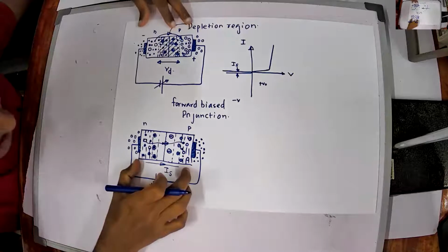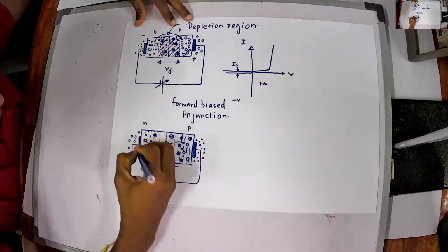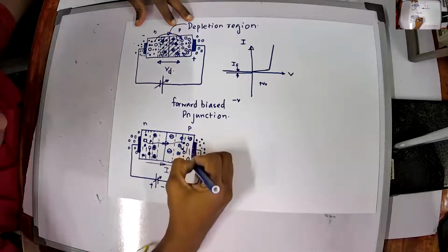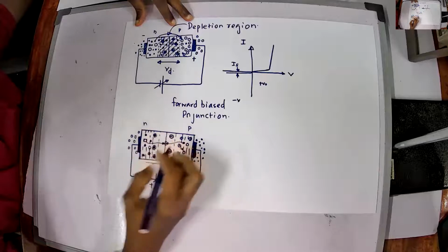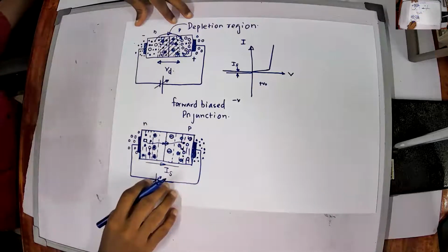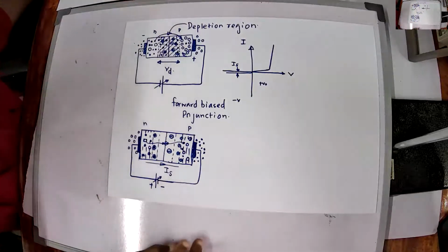And at that condition, I could say that the PN junction turns into a kind of parallel plate capacitor, which has two potentials across these two, and a dielectric material in the middle, which does not have any free charges which could contribute to the electricity.